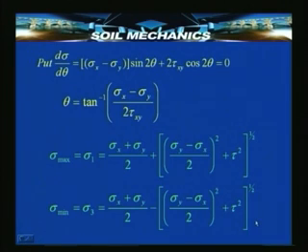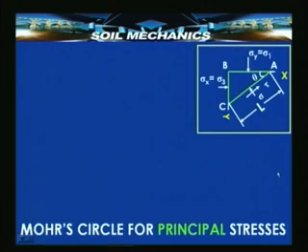So, it is possible to calculate the minimum and maximum by a simple differentiation and substitution of the condition under which the stress becomes minimum or maximum. Now, let us see once again the construction of a Mohr circle, but this time for a specific case where the principal stresses are known, or rather the principal planes are known. Take the key diagram once again. This key diagram is similar to the earlier one, but the only difference is here the horizontal plane AB only has a normal stress now. The shear stress is 0 on this because AB is a principal plane.